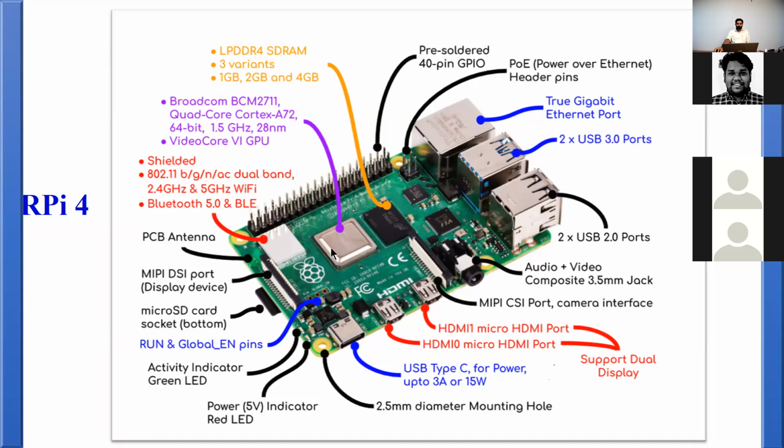The main module of your Raspberry Pi is a Broadcom BCM2711 processor with 1.5 gigahertz clock frequency and 64-bit architecture. We know that it is purely an ARM architecture. It is equipped with a quad-core, or 4-core, processor. We know that our laptops or desktops have a maximum of dual core, or 2 cores. Compared to that, this is a quad-core processor. The next thing is the different input output ports.